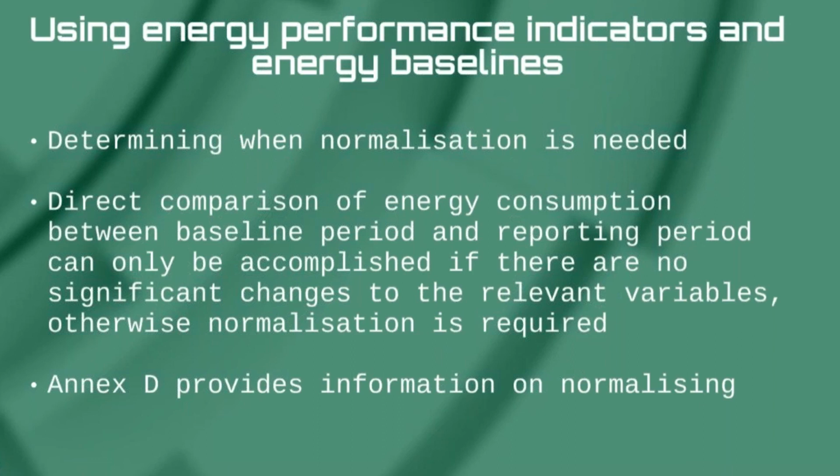Well, in an exceptionally cold winter, you'd expect to use more heating fuel, and that would mask any benefits from your improvement plans. You might end up deciding that your improvements have been a failure, quite unjustifiably, if you haven't made adjustments for the weather. So normalizing is very important when you're making those comparisons for different periods of time.